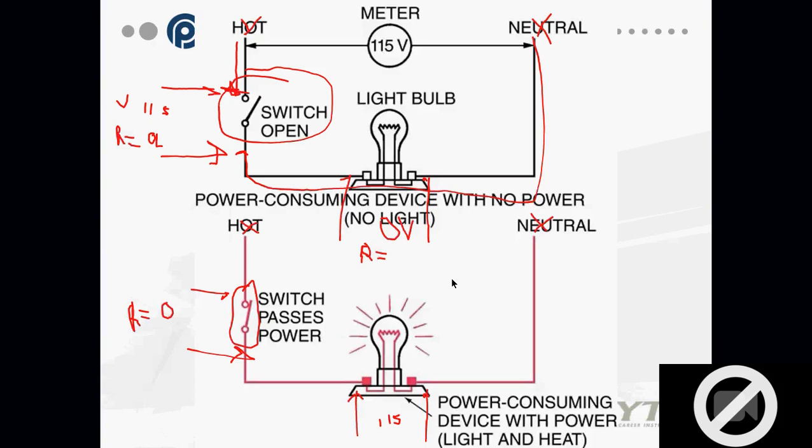Well, it could be 0, but that would be a problem, wouldn't it? It's some number. Resistance across a load is some number. What is the problem if I have a 0 resistance across a load? There's either a problem in the load or the line before it. If I have 0 in a load from here to here, I have a bad load. It's a shorted load.